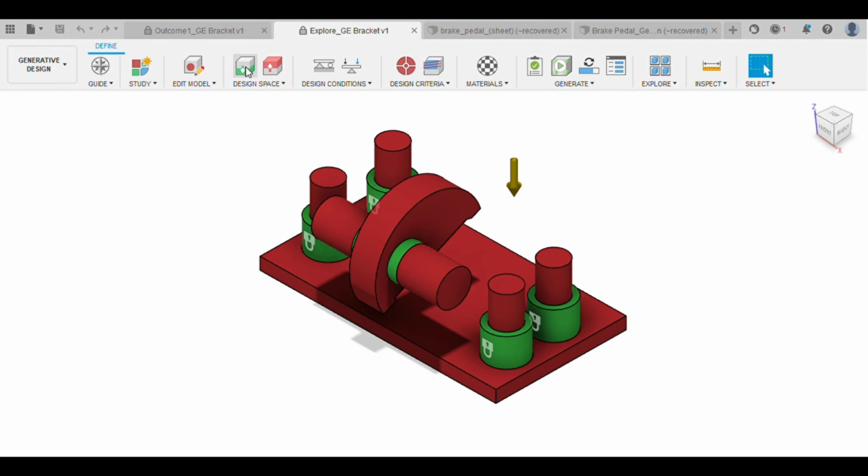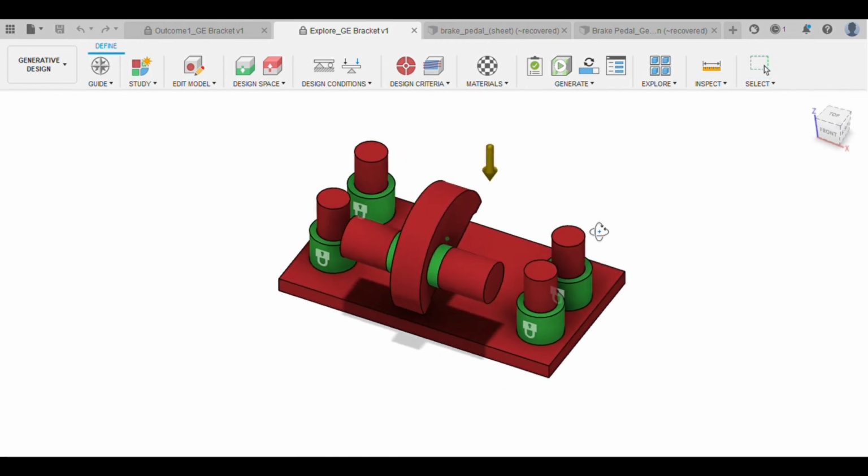Preserve geometry helps in incorporating what is required in the final shape. So certain things need to definitely be present in the final design. So for the features in the final design we use this preserve geometry. As you can see in the features, this preserve geometry has some functional requirements and functional strength considerations.